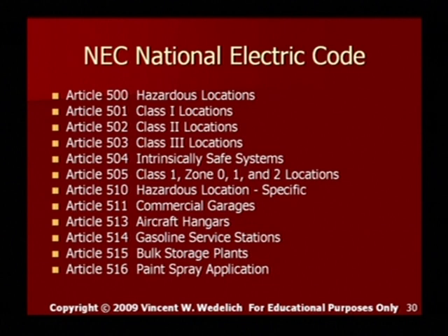511 is commercial garages. 513 aircraft hangars. 514 gasoline service stations. 515 bulk storage plants, and then 516 paint spray applications. This is an area, the paint spray applications is an area that really needs to be looked at, especially as a manufacturer. You specify equipment to be painted, and when they paint that equipment, they use explosive paints. And if you go into some of these mom and pop shops, you'll find out that those mom and pop shops are not using lamps that are rated for the hazardous area.